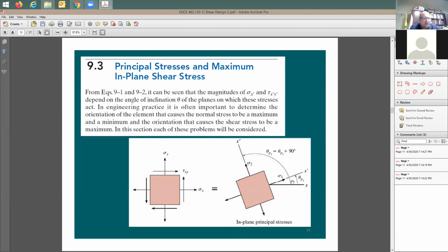With this angle rotation, you're going to find out that the stress is just changing. The amount of tension that you have here may increase a little bit or reduce. If one of the stresses here in the x direction, which means the tension stress or normal stress, if you like to call it this way, is going to be going higher in value, the other one is going to be going lower in value.